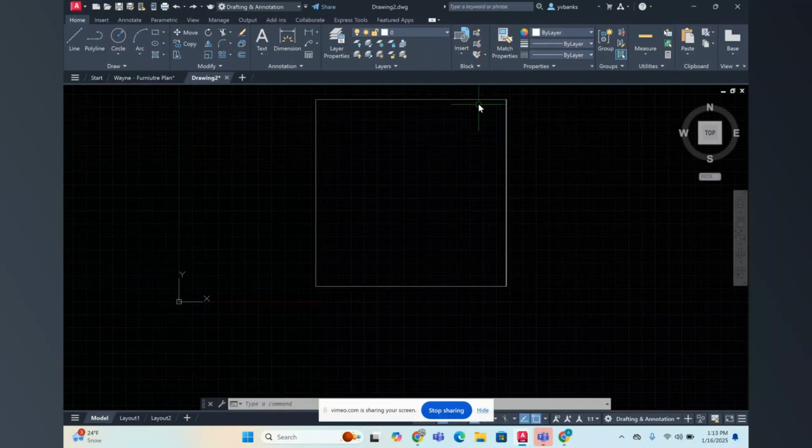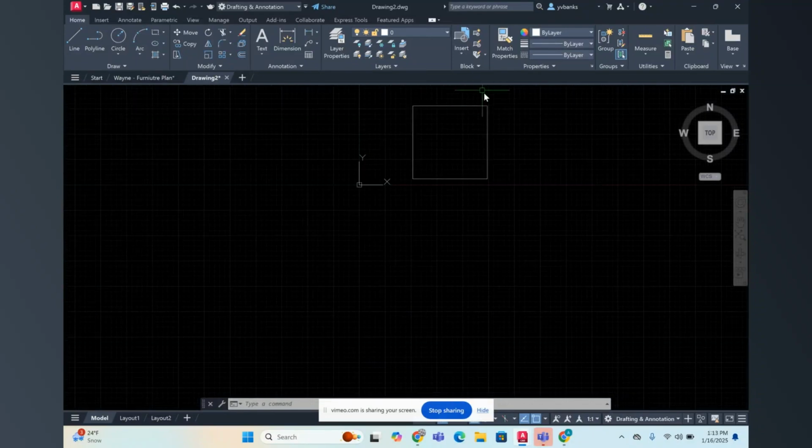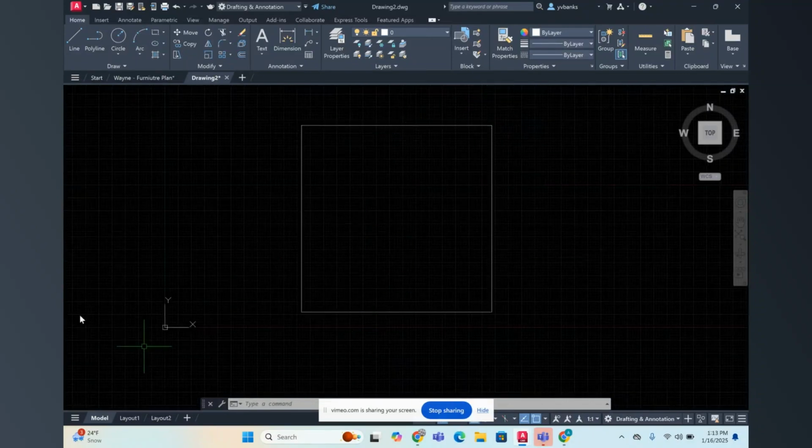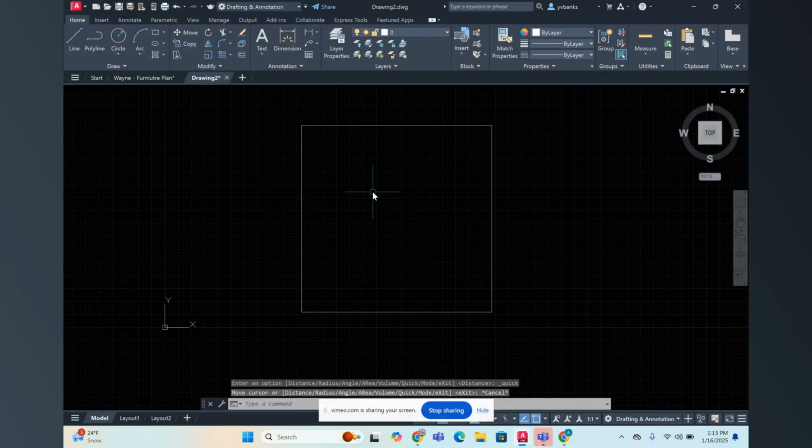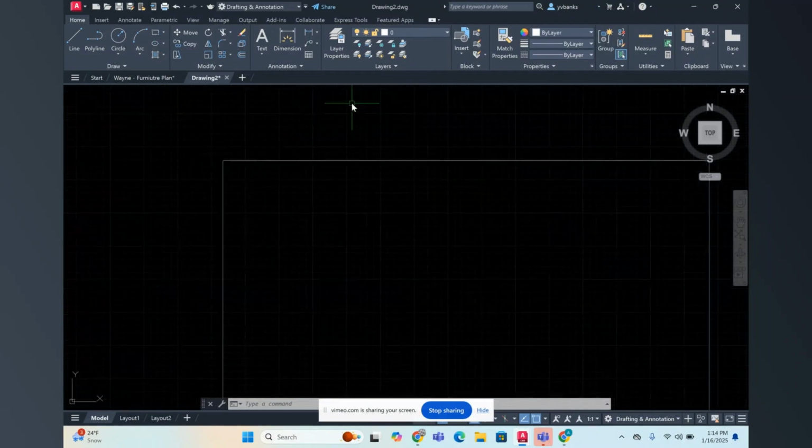First, in front of us right now, I have gone ahead and created a square that measures 3 feet by 3 feet. Using the quick measure tool, I'm going to check that measurement. And here you have 3 feet by 3 feet, with 4 right angles. We're just going to say that this is some type of end table, a plan view of an end table. However, our corners aren't going to be 90 degrees. We're going to round off the corners of this square.